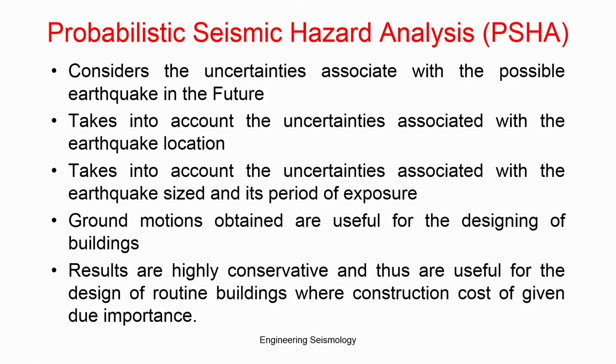Okay. So, then they ask the owner how much risk you want to take. So, I want to take 50% probability, or 25% or so, and based on that you will get a hazard value, depending on how much risk you want to take. That basically manages the cost and risk you want to get out of this. Because of that, this is more useful for buildings, because the building life is basically 50 years, or 30 years or 10 years. Depending on that, for a short-life structure you can take more risk, for a long-life structure less risk, and different combinations can be worked out in the PSHA procedure.